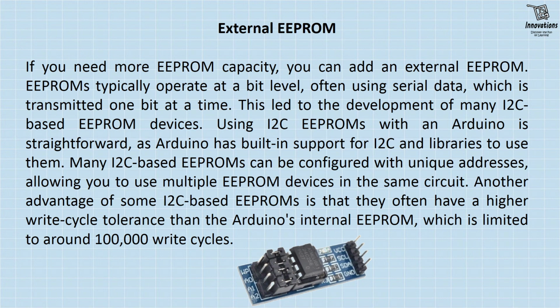Using I2C EEPROMs with an Arduino is straightforward, as Arduino has built-in support for I2C and libraries to use them. Many I2C based EEPROMs can be configured with unique addresses, allowing you to use multiple EEPROM devices in the same circuit. Another advantage of some I2C based EEPROMs is that they often have a higher write cycles tolerance than the Arduino's internal EEPROM, which is limited to around 100,000 write cycles.